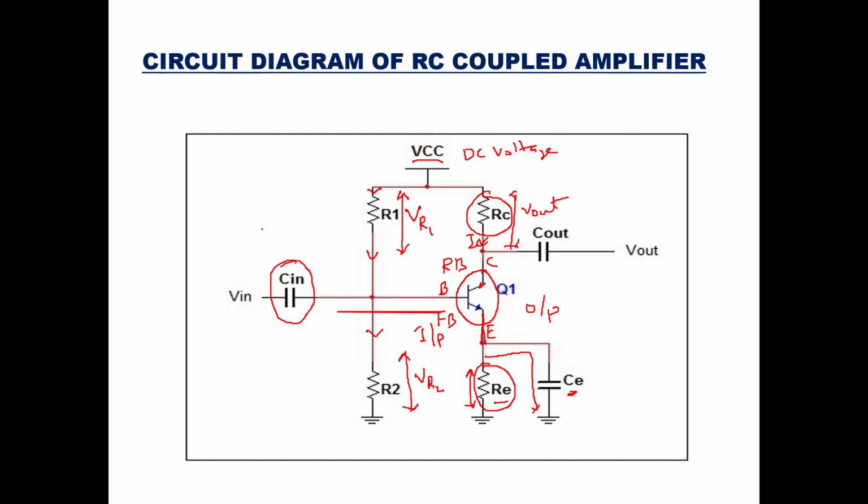So this is called as a blocking capacitor. Now this will block DC, and it will pass AC, so that AC reaches the base of the transistor. Okay, so this is your signal, whatever you are going to give here. So this will be your V in. Okay, and this is what the alternating quantity has to reach to the base of the transistor.